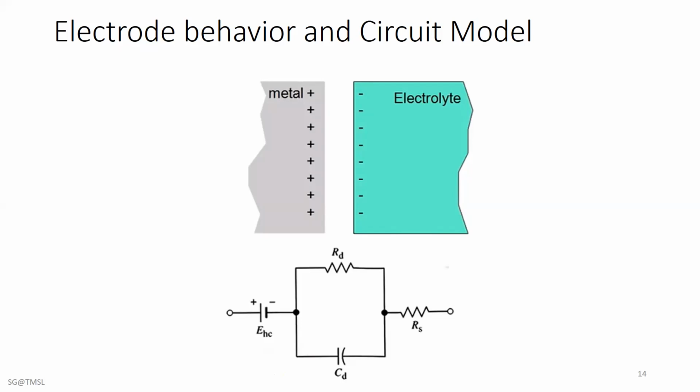The chemical activity that takes place within an electrode may cause voltage fluctuations, and may appear as noise on a bioelectric signal. This noise can be reduced by proper choice of the material, or by special treatments, such as coating the electrode by some electrolytic method. Such an electrode is prepared by electrolytically coating a piece of pure silver with silver chloride.